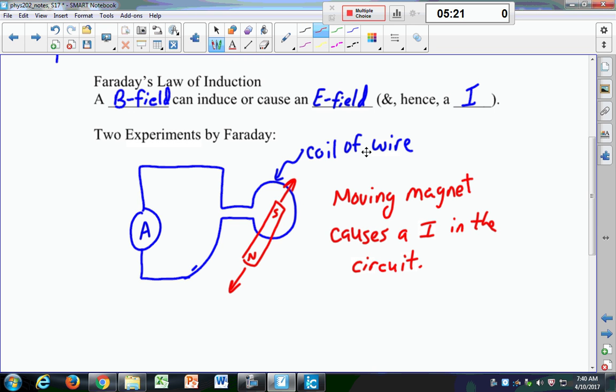So remember I showed you the video of the lady or the guy, I don't remember, that made the armature, and they used wire that had a thick coating. I said you could use magnet wire. This actually is magnet wire too, but it just has a very thin insulator over it so that when you wrap it up into a coil like we have here, you don't get currents jumping between wires, just so that they're insulated. Anyway, this is magnet wire. It's wrapped around a toilet paper roll, about 50 turns or so.